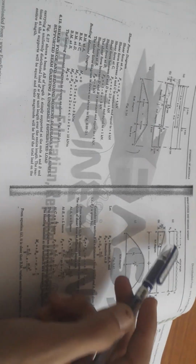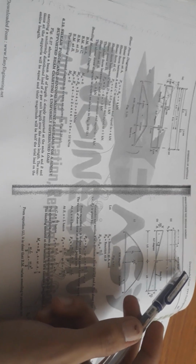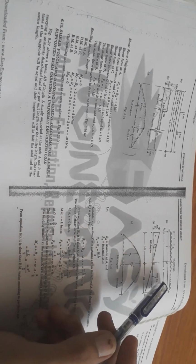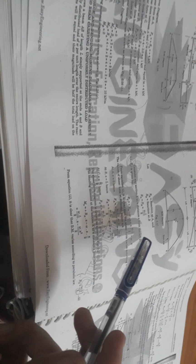Shear force and bending moment diagrams for a simply supported beam carrying a uniformly distributed load. Here it is Ra, it is Rb, this is small x, this is capital X, W per unit length. Here Ra is equal to reaction at A and Rb is equal to reaction at B. Ra is equal to W into L by 2.